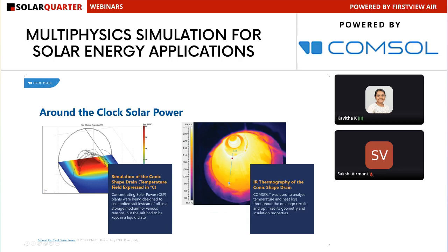The next user story is from the Italian utility ENEL and the Italian National Agency for New Technologies. They joined together to develop a new kind of concentrating solar power plant using parabolic surfaces. A concentrating solar power plant generates electricity during sunny hours as well as under overcast conditions. This new type of plant depends on molten salt as a medium for storing heat in large, well insulated tanks, replacing pressurized oil as the fluid for heat transfer.